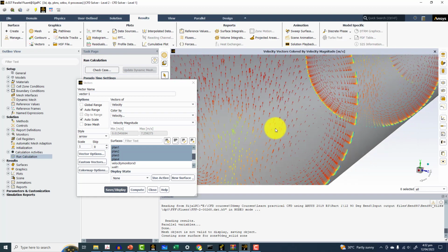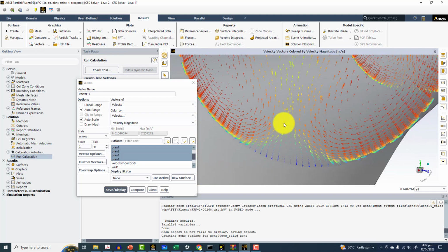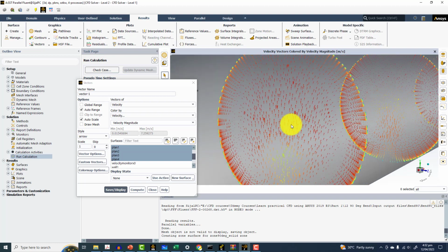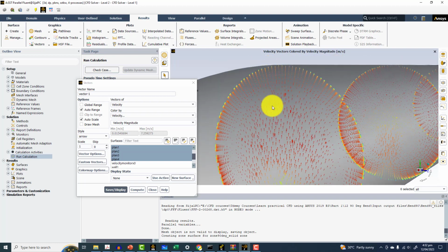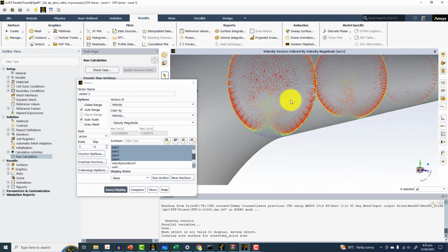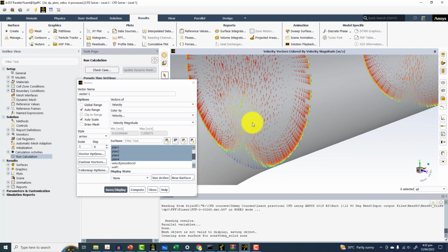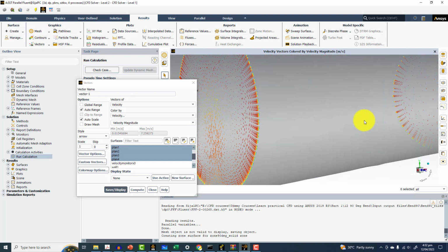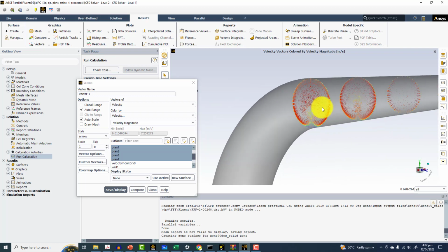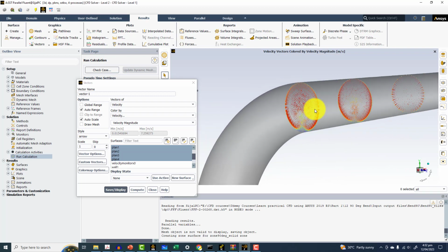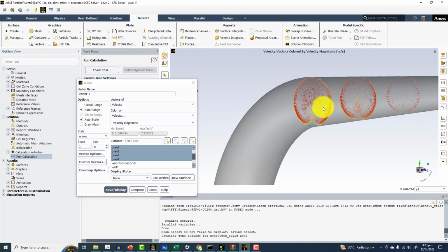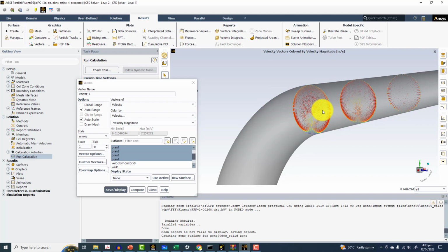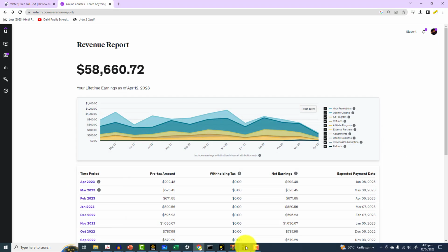You can see that we have a vortex where the flow is pushing towards the inner core from the outer side. So at the outer side pipe radius, the flow is being pushed inside. You can see this very clearly, and the same thing is visible here. This is the case where the curvature ratio is equal to 2. But if you go below this curvature ratio, you will see a stronger secondary flow. If possible, I can show you.